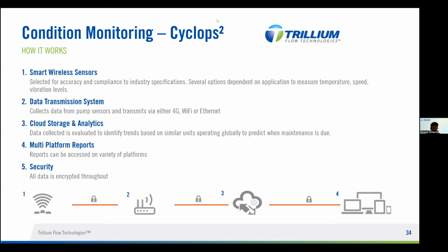Data are collected locally through a Bluetooth system module and transmitted via Wi-Fi, Ethernet, or 4G GSM to cloud. Transmission device is normally located in a small junction box, normally a 30 centimeters square junction box. The junction box is positioned on the base plate, or in case of vertical axis pumps, on the pump stool.